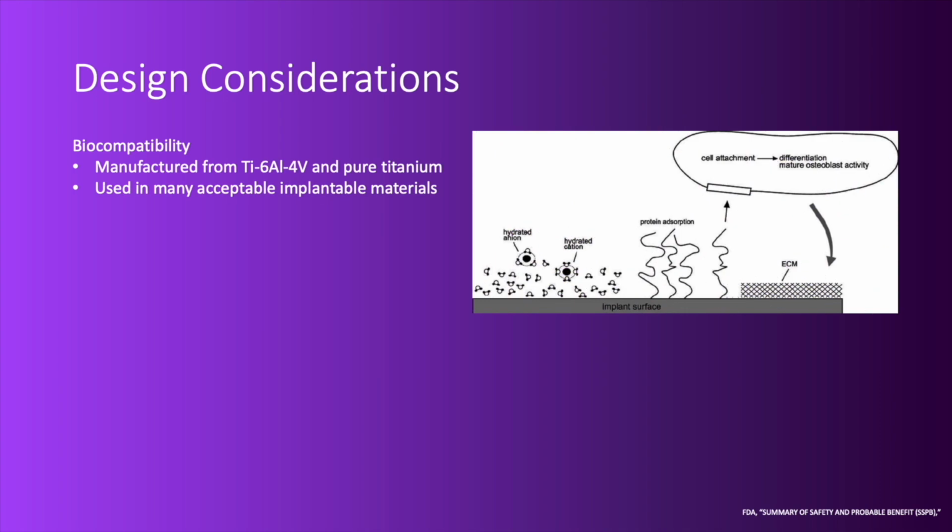The next design considerations are associated with the mechanical behavior of the implants, using testing procedures aligned with ASTM standardization. Torsion testing, involving fatigue-oriented cyclical tests of up to 10 million cycles, is used to validate the fatigue behavior of the implant, and bending testing to evaluate the maximum allowable single-point eccentric forces to be encountered by the OPRA implant system is performed on all components.